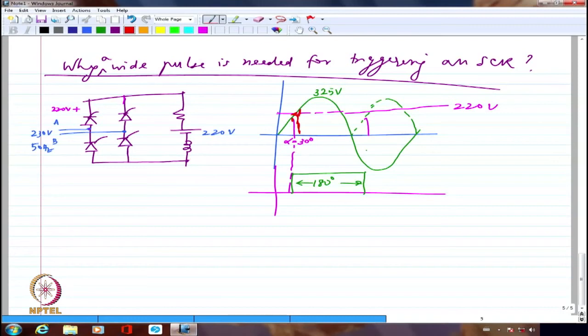When there is discontinuous current, I have to worry about the two values of voltages, which is higher and which is smaller. I have to compare the two. So in this particular case, it will start conducting only from this point. And then it might probably end conduction somewhere here. Possible. Right? And it will repeat itself again. So it may again start conducting from here and so on. This is how the current will flow. So when I have a battery, things become a little difficult for the devices to get into conduction.